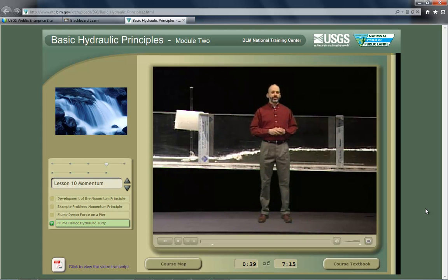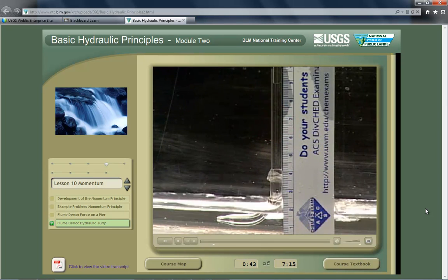So let's take a closer look at what we have at the upstream scale. We see there that the depth is approximately 13 millimeters from the bottom of the flume, and you see the meniscus is varying quite a bit. The velocity fluctuates quite a bit when you have very thin flow like that. But it's averaging at about 77 millimeters. So with those two numbers, a depth of 13 millimeters and a velocity head of 77 millimeters, let's now go to...